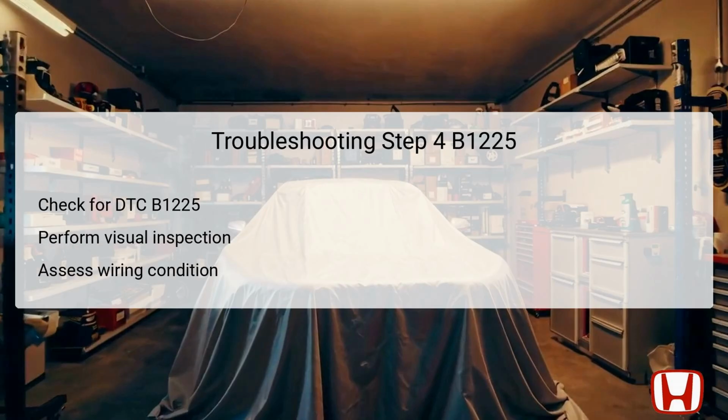At this stage, you will check once more to see if DTC B1225 is still indicated in the system after performing the self-diagnostic function. If the code is present, it indicates a persistent issue within the in-car temperature sensor circuit. This is a critical moment where you should conduct a thorough visual inspection of the wiring and connectors associated with the temperature sensor.